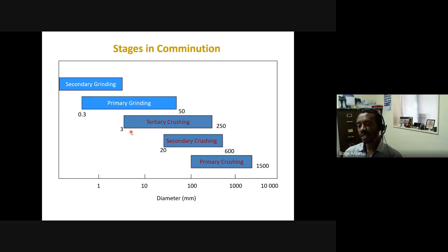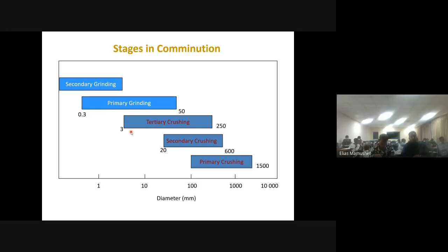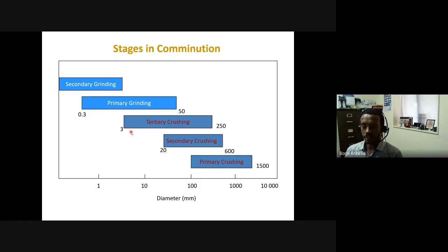So it is coming down to the method that we apply, so the force we apply to the rock. In a jaw crusher or a gyratory crusher, we're not hitting the rock with high force. It's a very gentle force, but that gentle force is enough to fracture the rock into a few pieces. So we're not smashing it with very high impact.